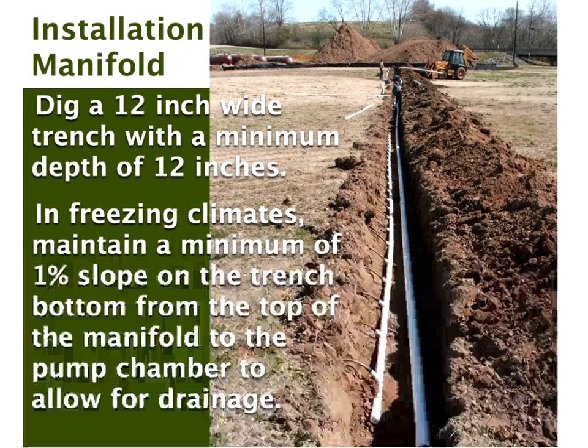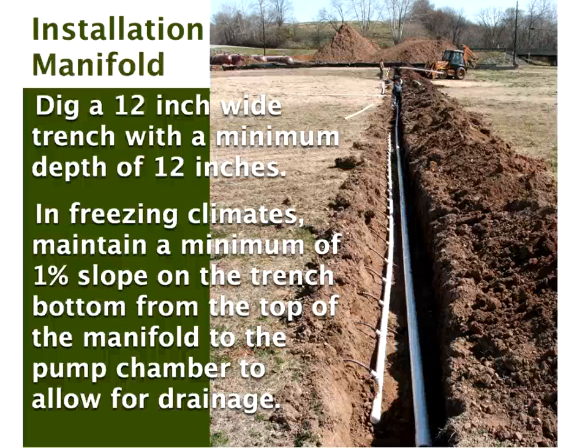Rodney, there was a question in the chat window which actually relates to that mound image, from Percy Johnson, where he was saying that the biggest issue they face in Missouri is seasonal high water table. So with the addition of drip to an above ground mound system, is that going to resolve some of Percy's issues? Yes, this is why mounds are used. It gives you the clearance that you need, both from the regulatory point of view and from the point of view of actually getting the treatment.